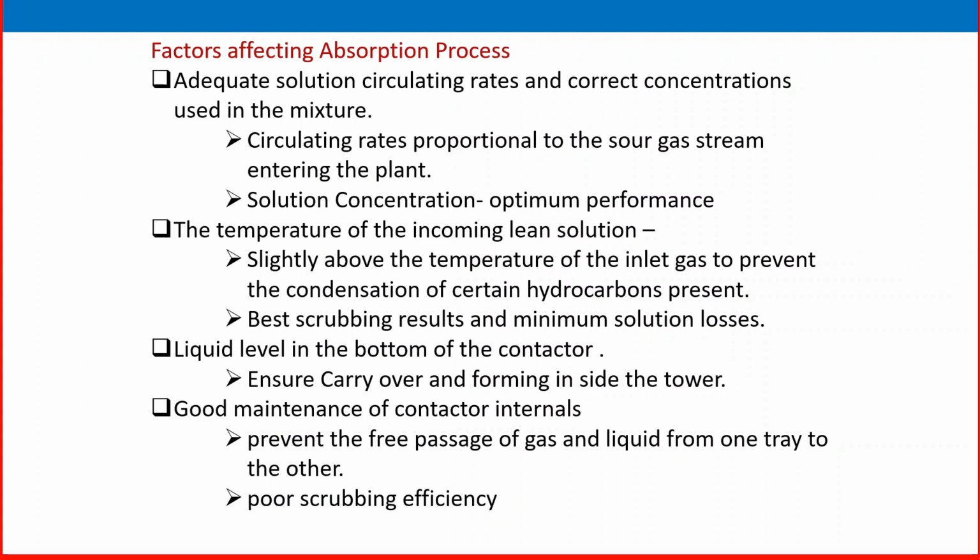We have discussed the internals. So internals should always be in good condition. Frequent maintenance, replacement and repairing will improve the performance. Otherwise, it allows the free passage of gas and liquid from one tray to another, resulting in poor scrubbing efficiency.